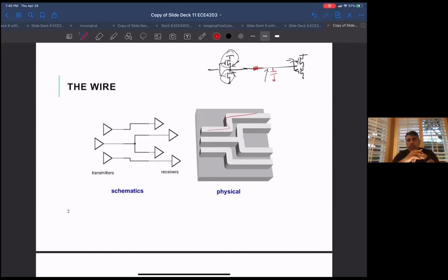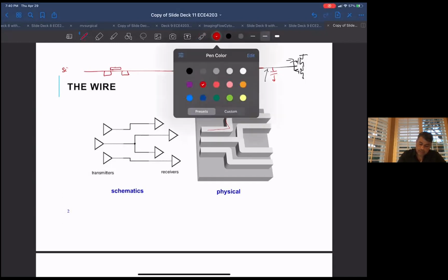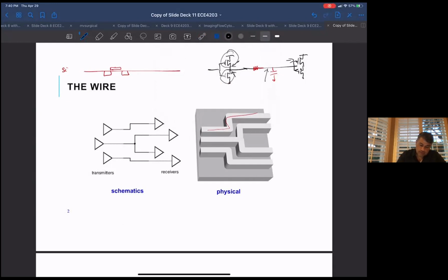We looked at the CMOS process technology. Basically, first you create the transistors, and then you put a dielectric layer, and then an interconnection layer, then a dielectric layer, then an interconnection layer. So if I was going to do a cross-sectional drawing, this would be the silicon surface. I would have my transistors like that. The gate capacitance would stick out, and then I would have some contacts potentially going to drain, source, and to your gate.